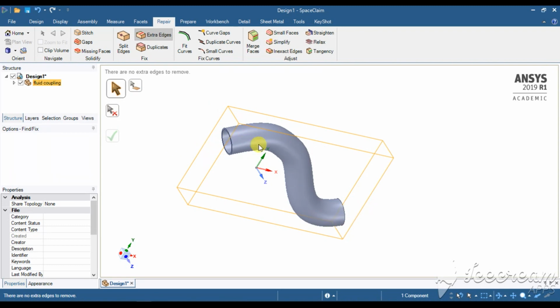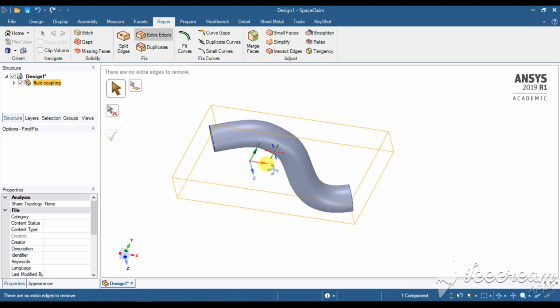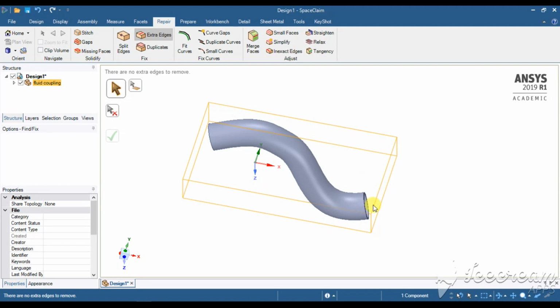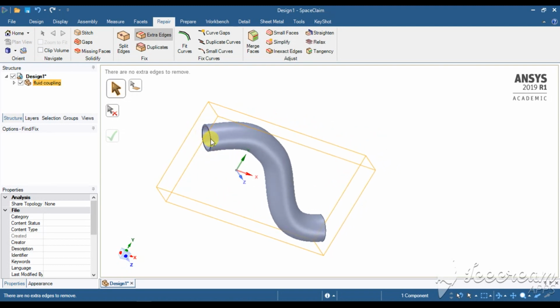But there is a contour section, an elbow type region, so that there is a change in pressure of the water flowing into the pipe, and also the velocity, and we are getting a different mass flow rate at the outlet than what I have provided at the inlet. So I'm going to perform a steady state analysis in this condition.